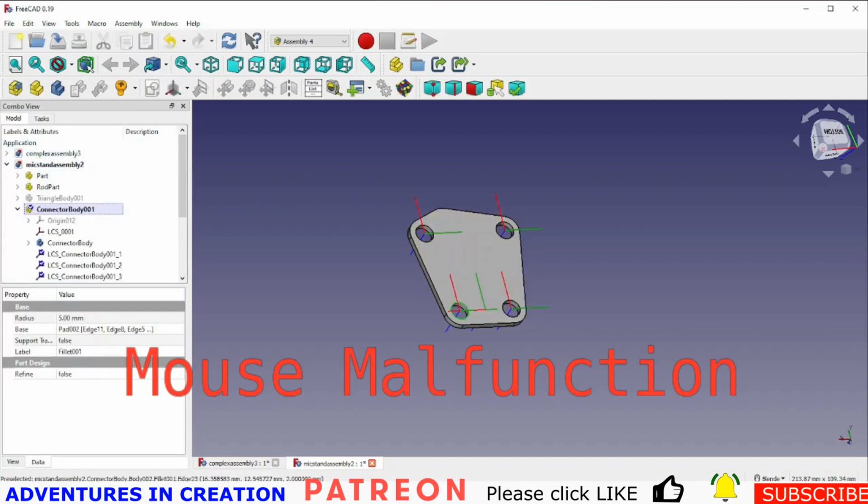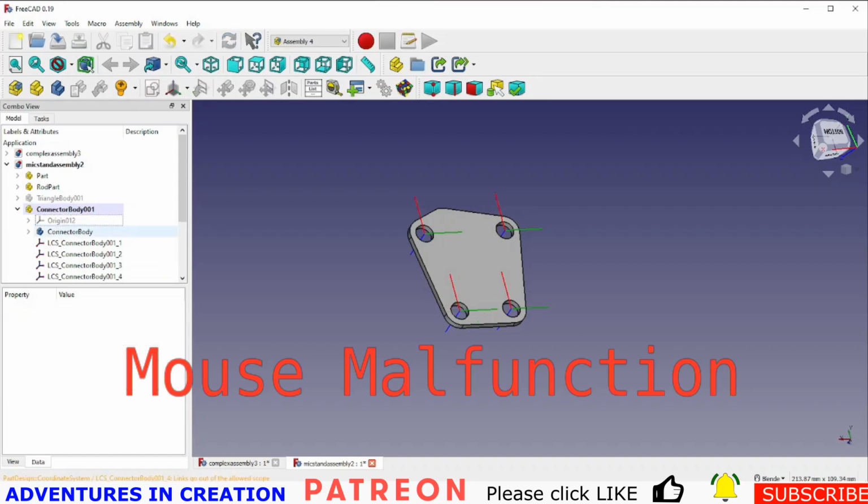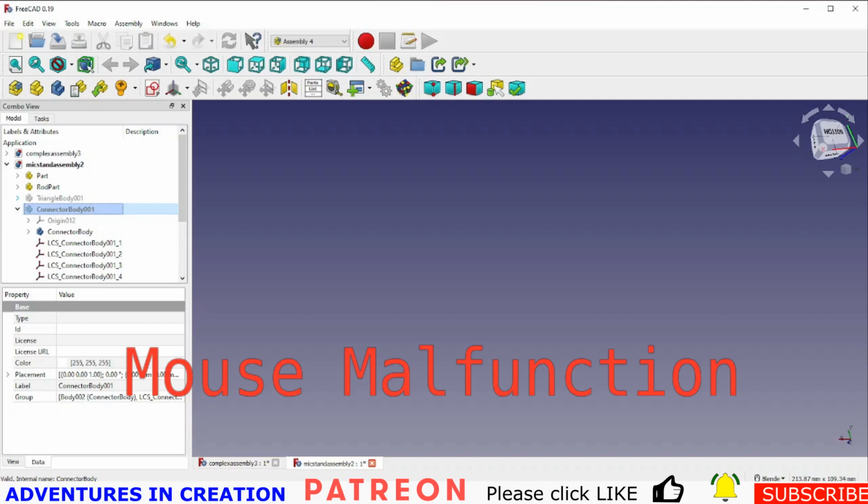Now for this connector body, I have 4 LCSs that are lining up with the holes. And in fact, I do have a spurious one on here. I've been playing with this stuff, so I may have added an LCS when I was playing with it earlier, so I'll just get rid of that one. Of course, every part has an origin LCS, but you don't have to have that switched on. So now I have 4 LCSs in that part. I'm just going to switch that one off, and then I'll go to the next one.